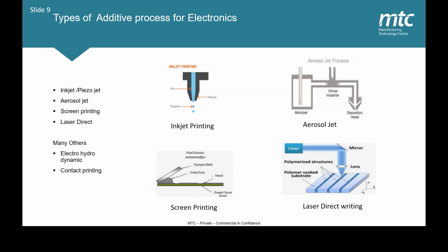An atomizer generates an aerosol of material droplets using ultrasonics or a pneumatic means, which is then carried by a nitrogen gas stream to the deposition head. The stream is then sprayed onto the desired substrate. The deposition head can be mounted on a multi-axis stage to follow the contour of complex non-planar surfaces. In addition, the high-density aerosol consisting of micro droplets can be focused to produce line widths from 10 to 150 microns and thicknesses from 10 nanometers to 5 micrometers.